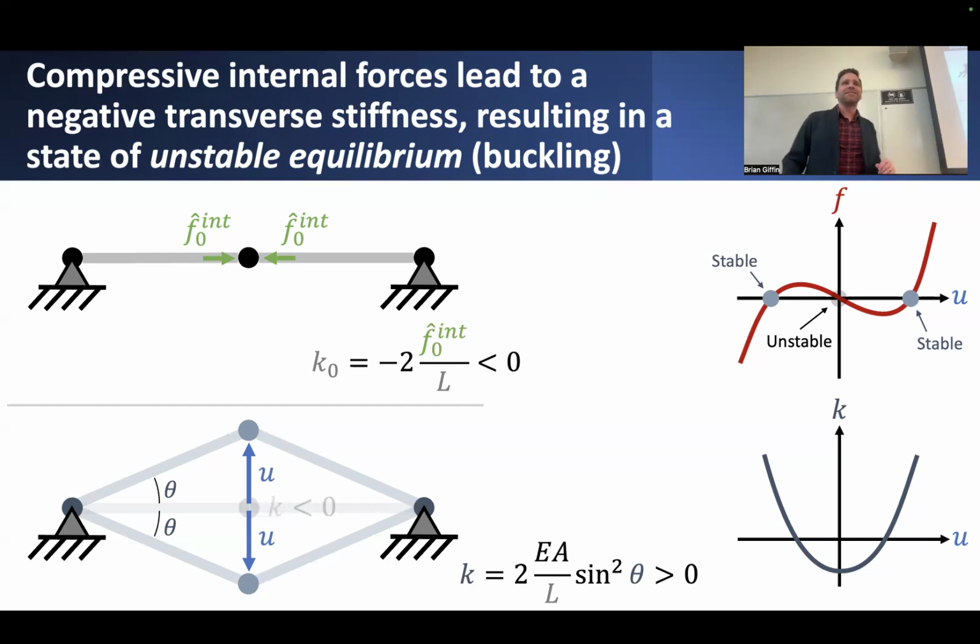One corresponds to this unstable configuration of a perfectly straight two-element problem like shown in the figure at the top. And there are two potential equilibrium configurations involving some kind of jump or displacement of the structure away from that perfectly straight configuration, either upward or downward. Either of those configurations corresponds to a state of zero transverse applied load, and zero apparent internal force within this assembly.